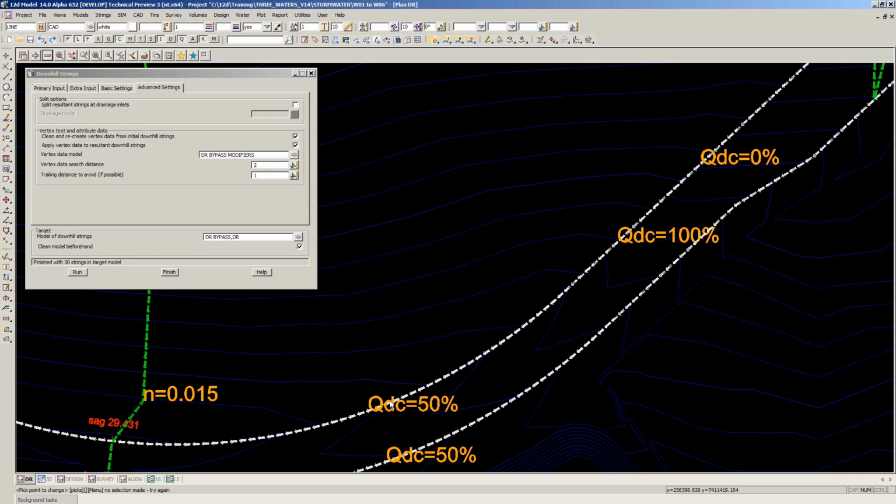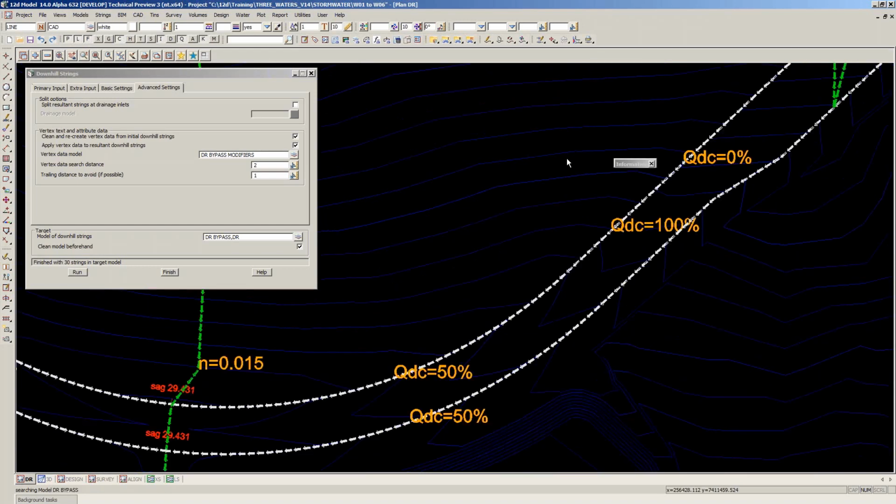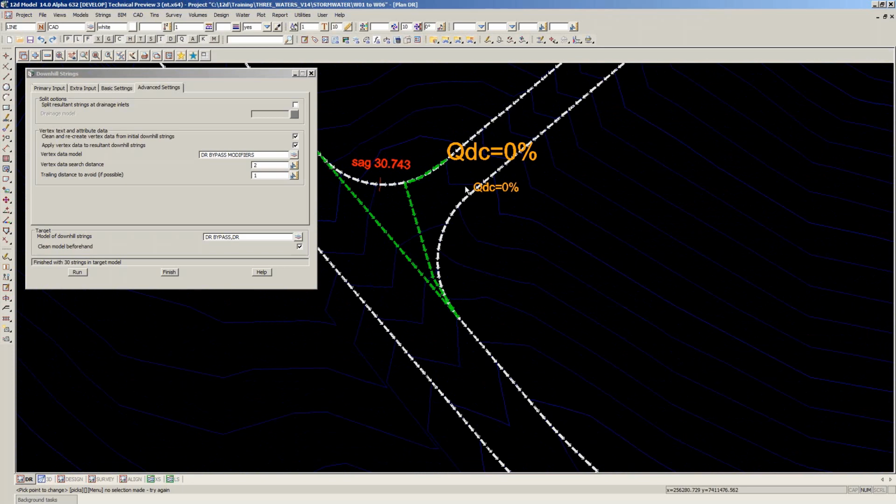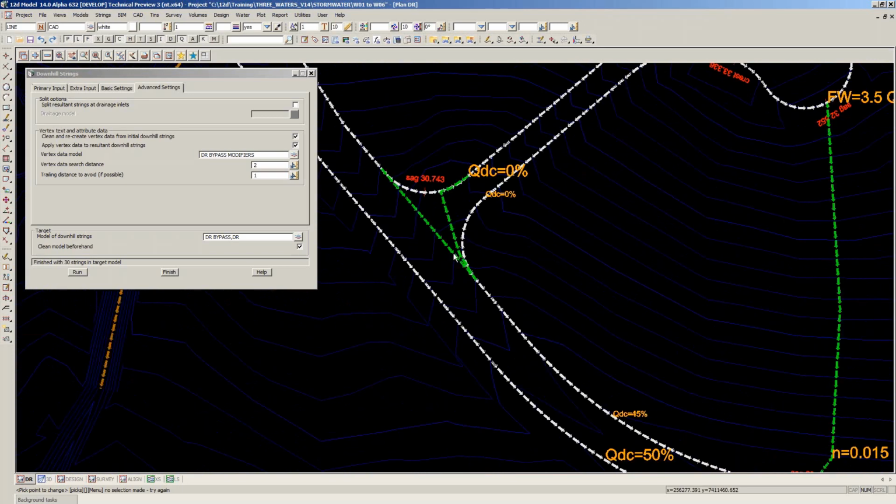So if I imagine there's a node here, and this is the top of the reach here, by the time I get here I'm about a third of the way down the reach, say. And so the flow rates would go from 0 to 100% of the flow, but I'm going to say nothing there, and then suddenly I'll get all of that sheet flow starting to accumulate into the channel there. And I think that's probably the most accurate way of modelling it when the road's in super elevation like that.